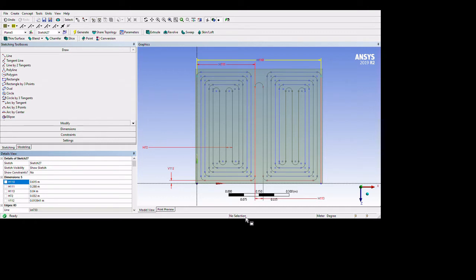The first, what we call tubing, and the last tube, the space between them is 0.615. The space of the one absorber loop from start to end of a single absorber is 0.288. This is the connecting section of the two absorber loops, and the distance between them is 0.04. And in the middle, for geometrical purposes, to simplify the geometry, we had to change the pipe distance. In these center sections, in both absorber loops, the pipe distance is 0.032.